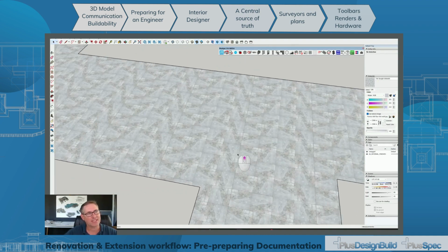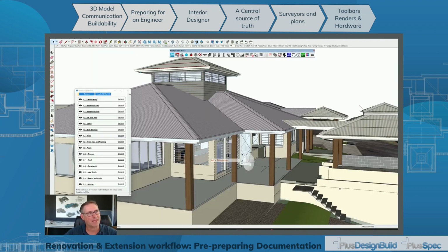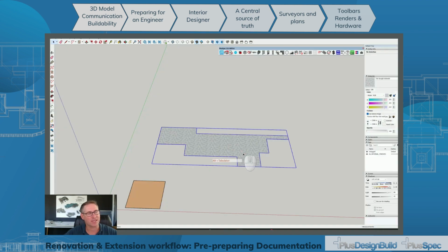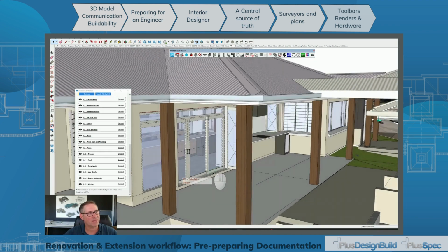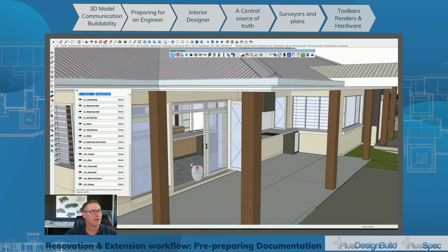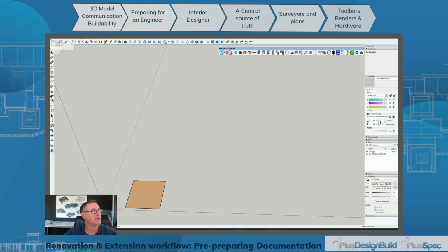And so what I did is I created my texture and I put it in here, but how did I get it from here back into the model? Well, the answer is that if I went into here and said delete this, say, and I went back to my model and went inside and I'm going to just open up the door here. I'm going to select the flooring, I'm going to go copy, Control C, I'm going to go back and I'm going to go edit, paste in place. Guys, I use this all the time.